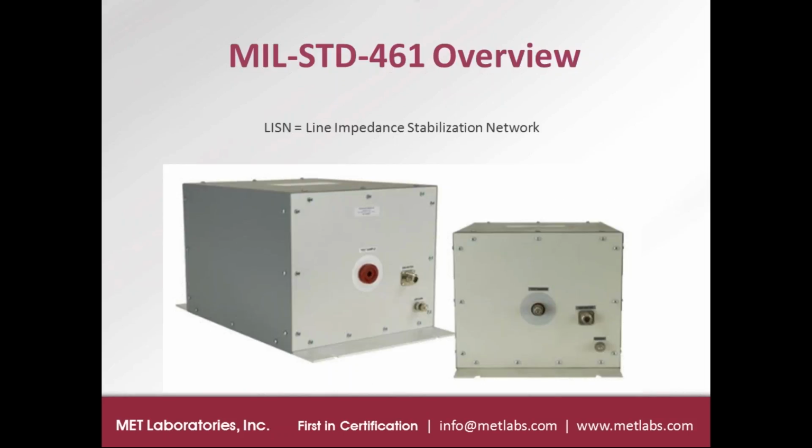This is just a photograph of a couple of example LISNs. They usually have a metal enclosure around the circuitry. So from the outside, they just appear as a plain chassis, and they have ports in the center, that's the circuit that goes in series with each power conductor of the input power to the equipment under test. And in addition, in parallel to that, they have a coaxial measurement port, which is protected by a capacitor so that no DC can come through into the spectrum analyzer input, and that allows you to take the voltage measurement across the frequency range off of the individual power conductors.